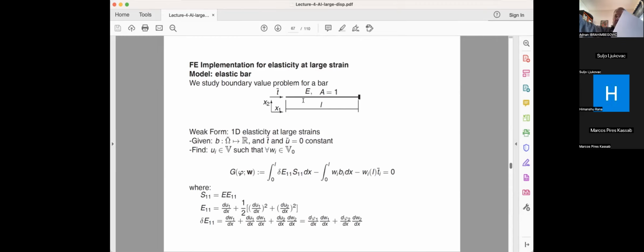So basically you have a unique property of the geometrically nonlinear problems that next to the usual stiffness concept, you have something called geometric stiffness, that basically this pre-stressing will turn the structure able of undergoing certain strain. And I'll give you maybe homework to look into that, how this is handled. So describing a situation of this kind, I apply the virtual work method to a bar, which is initially of the length L, and the work of internal force is expressed as a single stress component times a single strain component.